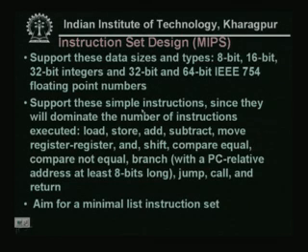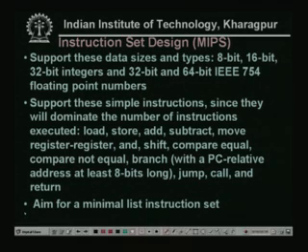It supports these simple instructions since they will dominate the number of instructions executed: load, store, add, subtract, move register to register, and shift, compare equal, compare not equal, branch with a PC relative address at least 8 bits long, jump, call and return.